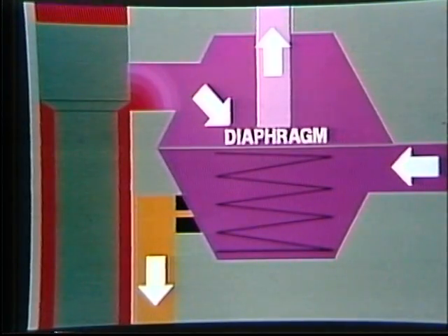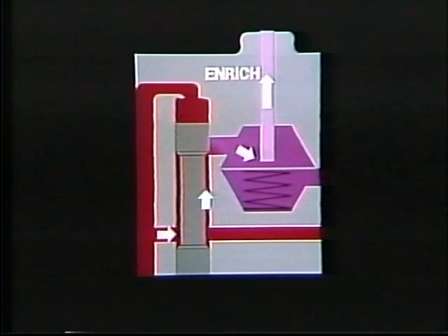The pressures are related. When lower chamber pressure is reduced, the diaphragm moves down to reduce upper chamber pressure accordingly. To enrich, more injection fuel flows when the pressure drop is greater at the slit. It's easier for fuel to get through. Pressure drop is increased by increasing the difference between system pressure and lower chamber pressure. That's sometimes called pressure differential.